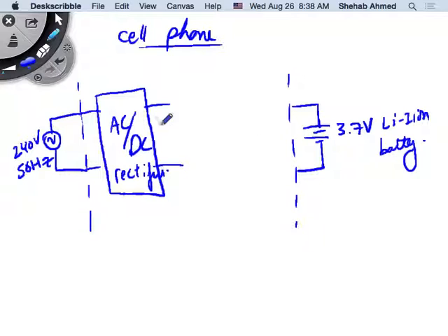We said batteries like to be treated nicely, right? So typically before a battery, we will also have to have a converter. What kind of converter did we put in the project? As a block, what was the function of the converter? It took what? It took this rectified step down AC voltage. After we rectified it and stepped it down and rectified it, it was DC, right? It was DC, but coming from AC, right? It was AC coming in after a rectifier, and we had some DC at the output of that. That DC was coming from the AC supply.